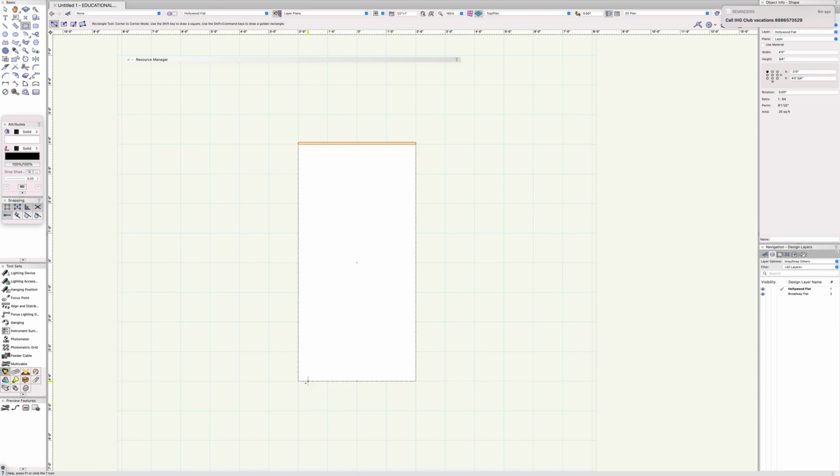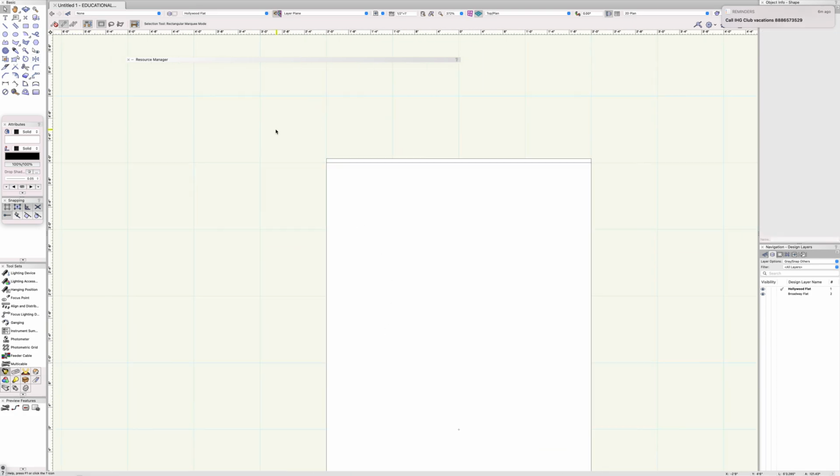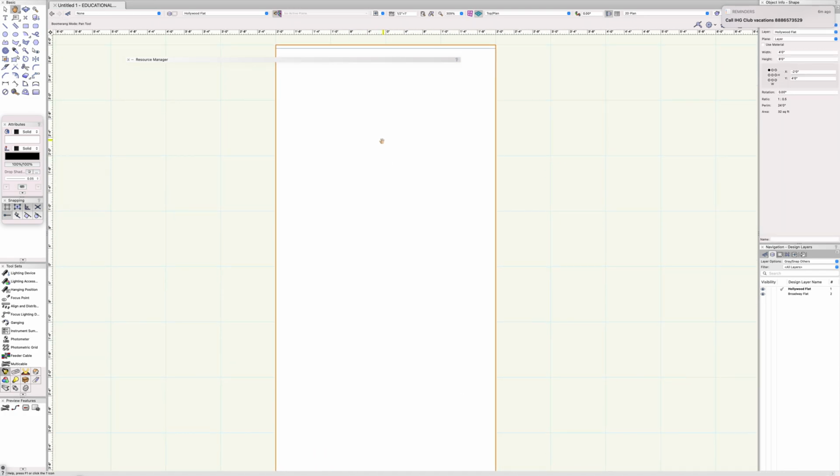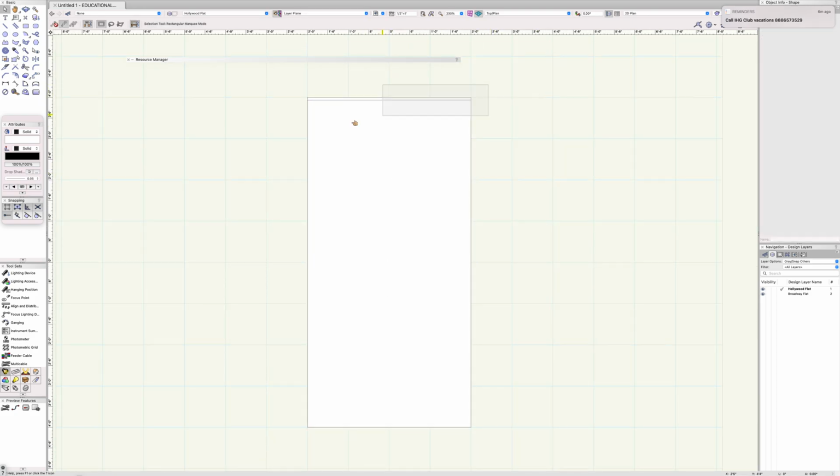Now I can draw another toggle up here. One way, I can also copy and paste it. Another way is that I can mirror this. I just wanted to make sure that it has been toggled correctly on the top corner. So this is on the top corner. Now if I select this toggle here and give the command mirror and bring it into the center, this will basically mirror the top toggle at the bottom. So now I do have top and bottom two toggles.